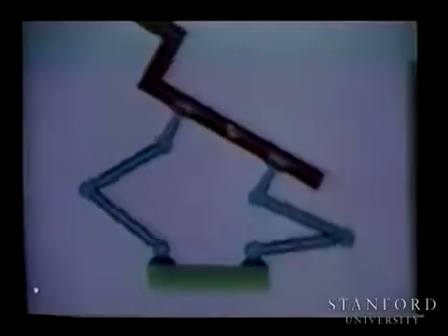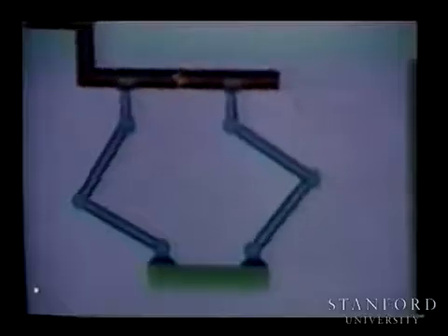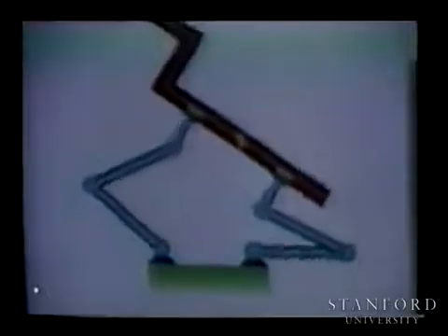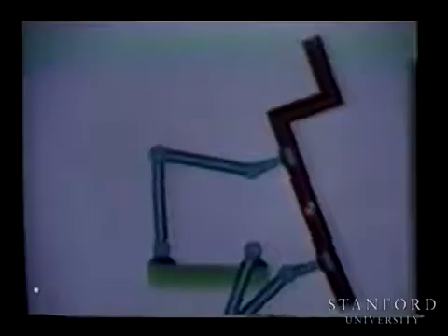These were developed in the late 80s. I mean, here is a very nice example. We are following this racket without any specification. Just the contact forces are driving this motion. So force control is very important, not only for compliant motion, but when you do cooperation between multiple robots, it is also the same requirement. You need to be able to control internal forces, otherwise you will break the object.